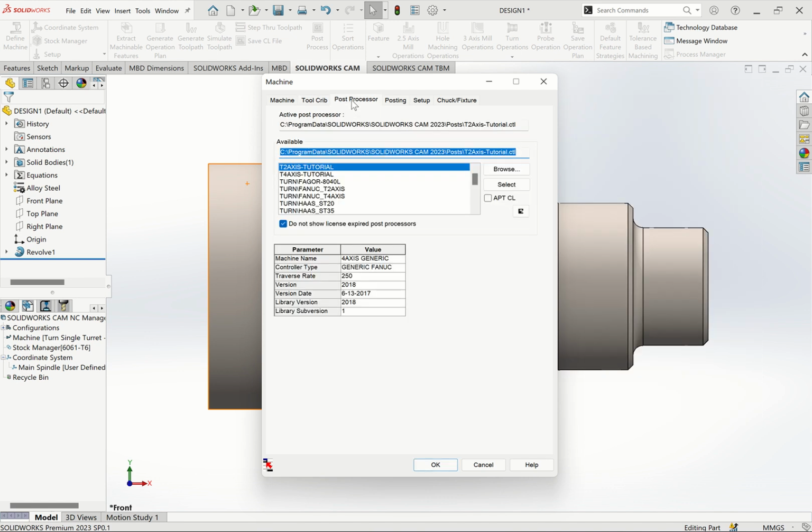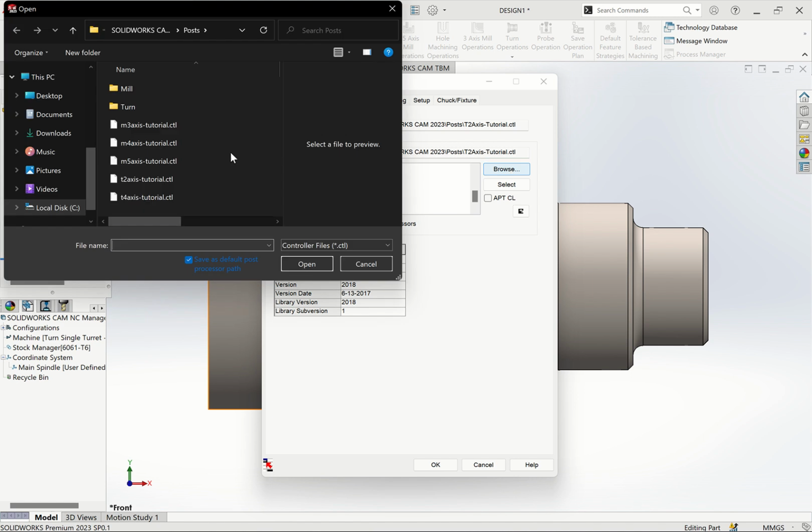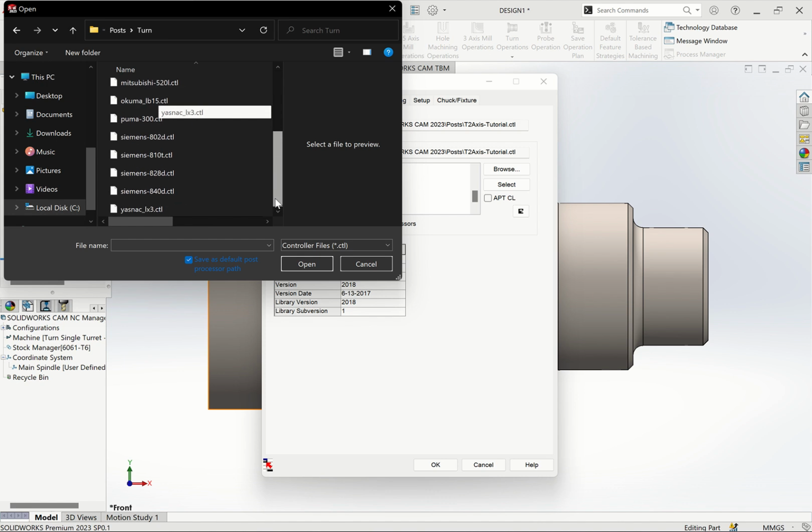You can go to post processors. Post processor is which kind of machine are you using? If you're using maybe the controller Siemens 808, 828, 840, or Numeric 1. If you're using Haas, maybe GSK 25i MC or TC, it depends on the controller. So you check on which controller. In case it is not here, you can also browse. It goes direct to where your machine is. You have the milling, you have turning. You click on turning, all these controllers will come here.